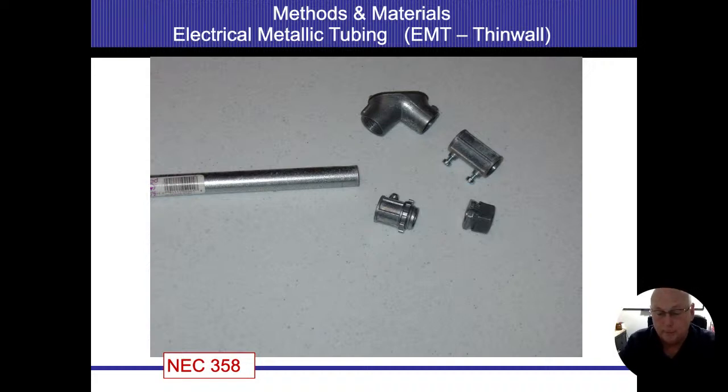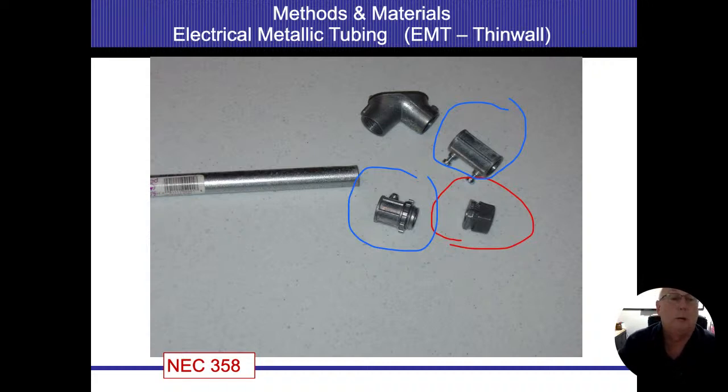I do want you to look at some of the fasteners that are present on here. These fasteners, such as this one right here, these are compression fittings. The compression fittings are only supposed to be used outside. What I'm going to circle in blue here, the ones with these screw fittings to tighten everything up, those are not to be used outside. Those are indoors only, all right? But the other ones are through. So the size of the conduit and the pipes determines how many wires and what size wires we can pull through there. Quite frankly, we don't really notice too many problems with this.